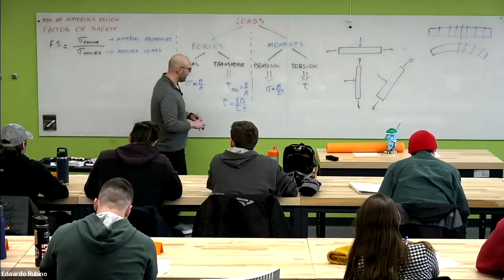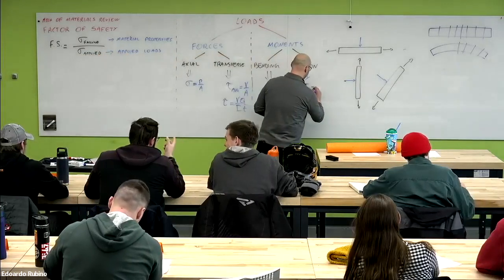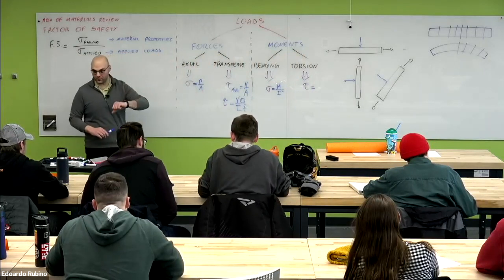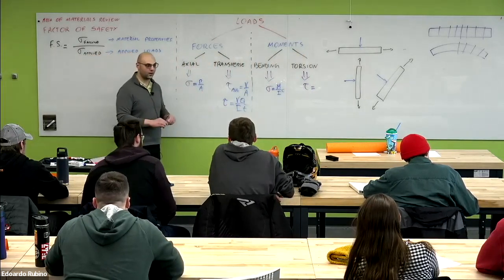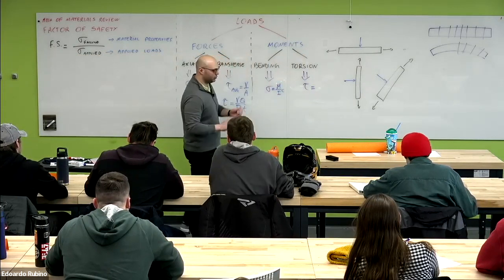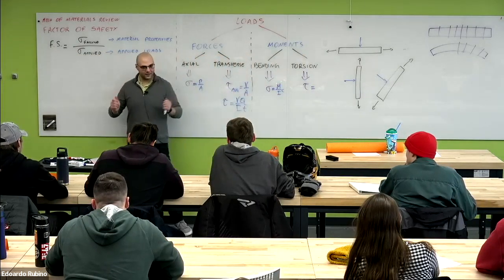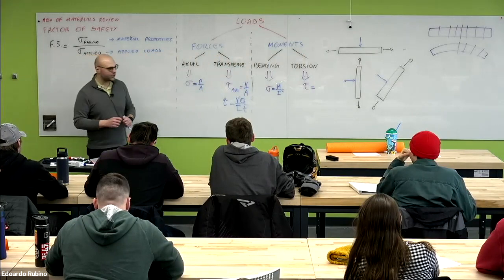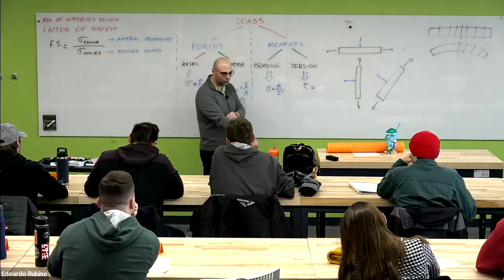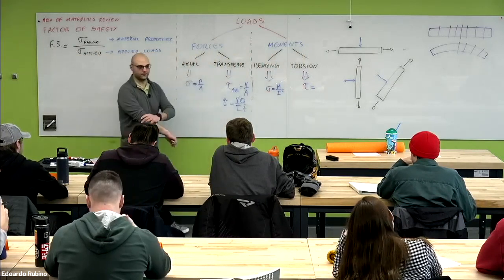And then we have the other load that is responsible for shear stress in our material. We have a torsion, it's like twisting our beam. Do you remember the equation that we have to use to determine the shear stress due to the torsional moment?